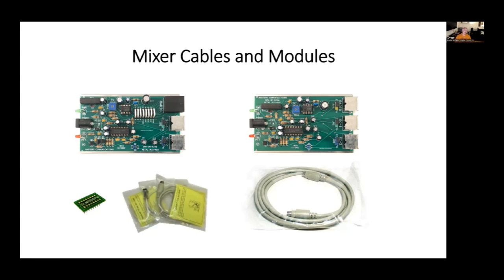And when it gets sent to you, we may have inadvertently left them in the 9600 position. So if you buy one of these from us and it doesn't work, I apologize up front. It may be simply that we need to take 4 screws out, slide the board out, look at these jumpers. Again, they're mechanical, no soldering required. They may need to be jumped in the opposite position and into the 1200 position to make them work.